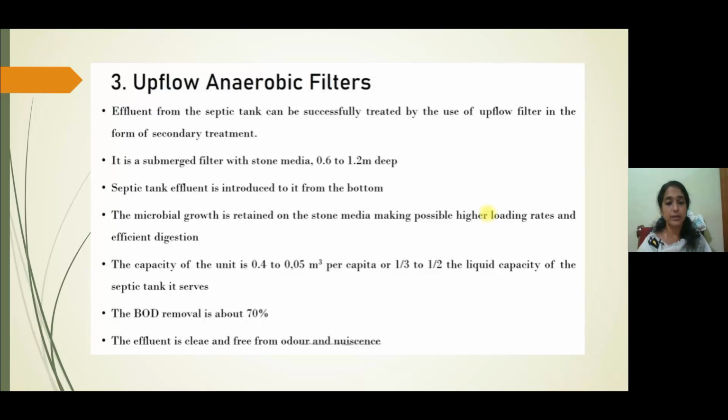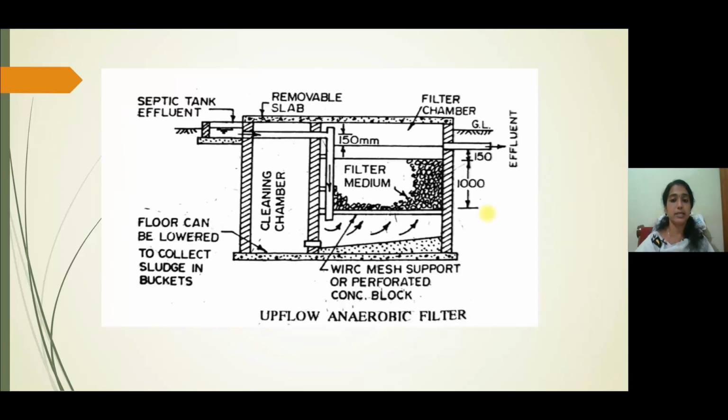The capacity of the unit is 0.04 to 0.05 meter cube per capita, or one third to half the liquid capacity of the septic tank it serves. The BOD removal efficiency is about 70%. The effluent is clean and free from odor and nuisance.